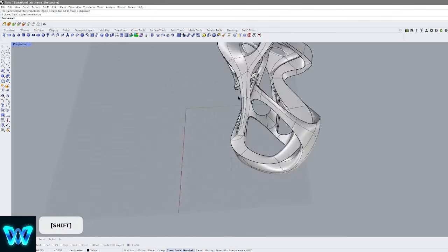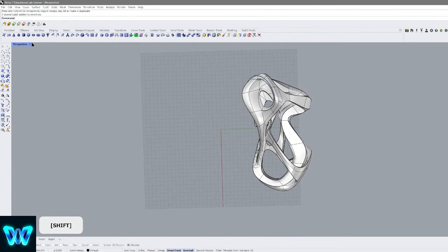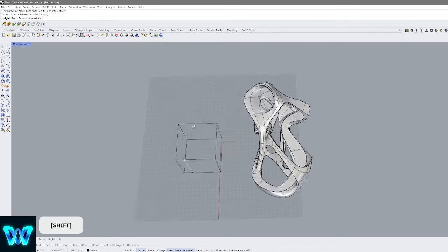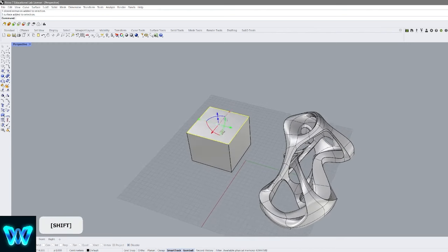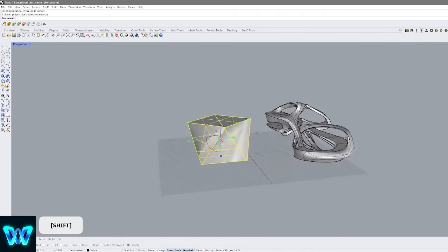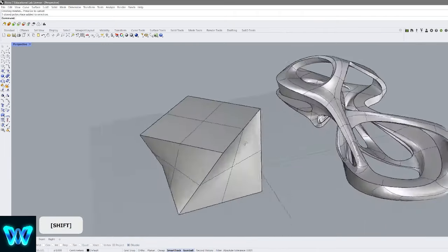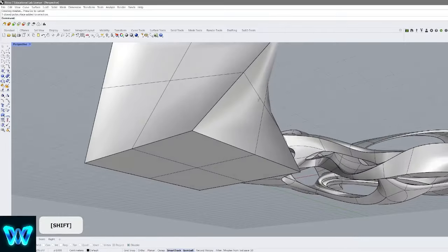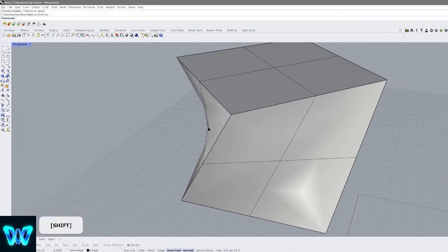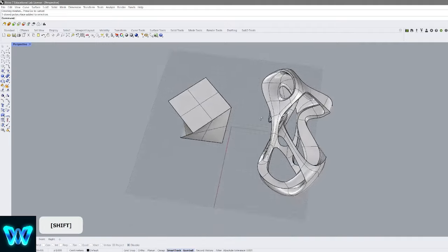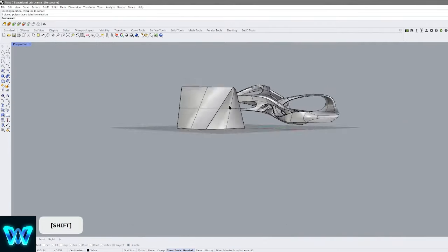The thing about subdivision tools is that they're different from the other 3D types of objects that you find in Rhino. So in this case we have polysurfaces, which would be this one right here. This is a polysurface. It's called a closed extrusion, but in reality it's a polysurface. The moment we twist it and do something with it, it's still a polysurface, which utilizes NURBS to create these curved forms of faces. Because in reality, mathematically, it's impossible to get these surfaces. So NURBS uses a specific technique of mathematical algorithms to create these types of surfaces.